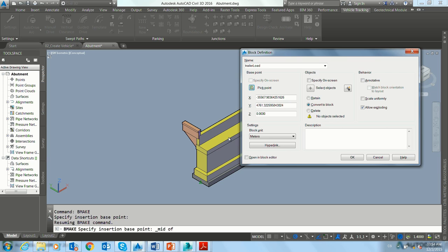However, don't forget that there are tires. Depending on the diameter of the tires, my trailer and load must be above these tires. So I have to move the value to minus 0.9 meters. Basically, I have to move it up above my wheels, above my tires.